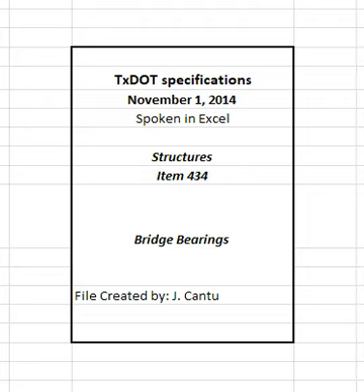Adhesion testing of laminated pre-qualification samples will be performed by the department in accordance with TX 601J, Part I. Adhesion Test Method 1. Bond failure between the elastomer and steel laminates must occur as stated in this test method to constitute a passing test result.